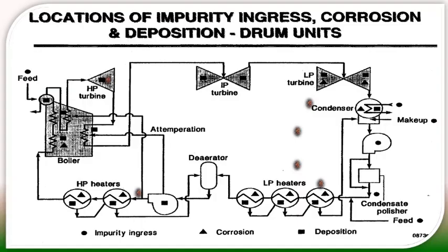There are three main reasons for water treatment. The first one is prevention of corrosion of material in the boiler feedwater, steam and condensate flow system, and elimination of formation of internal scale, and economic boiler operation without carryover of any solids with steam, like silica. Common feedwater contamination is what forms the boiler deposits.